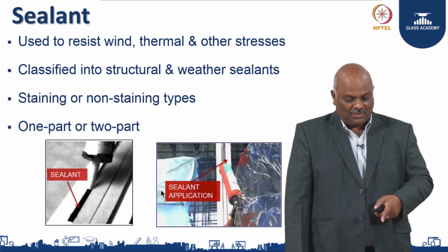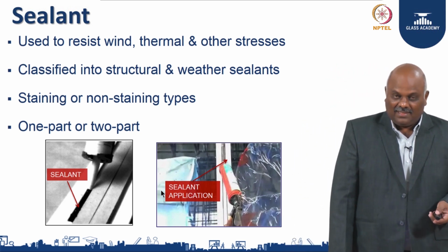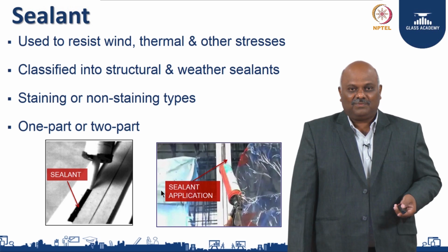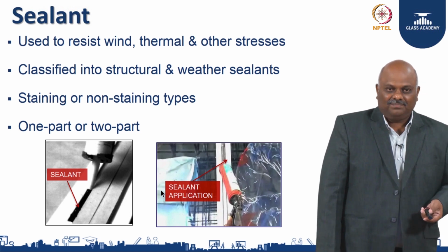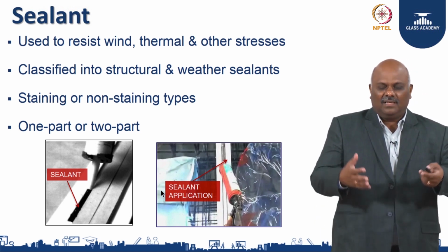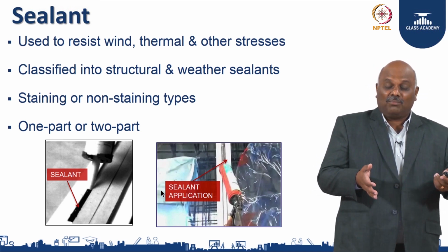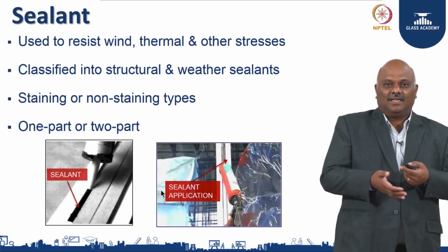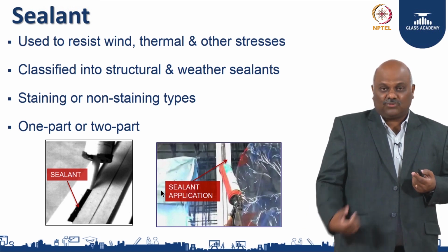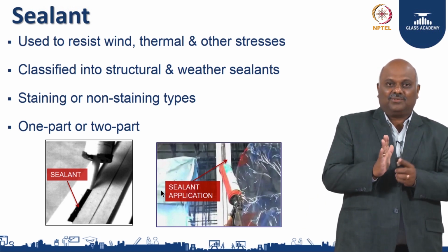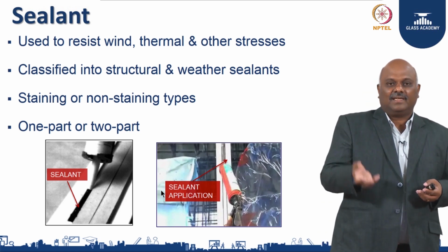Sealant, we should have seen this slide along with the double side tape. However, this is a material which has been an invention of 50 years now, I believe. So, it is a byproduct of petrol, and yes, this material keeps any bonding, they bond the structures together. They have high tensile and high shear stresses. So, they can be used as a structural sealant, it means holding something structurally to any element, or weather sealant, it means you can seal a joint not to let air or water go in.